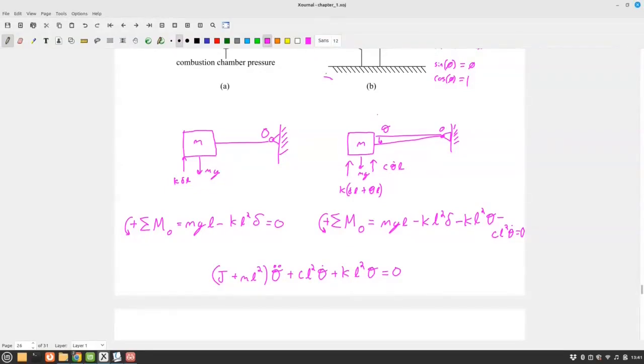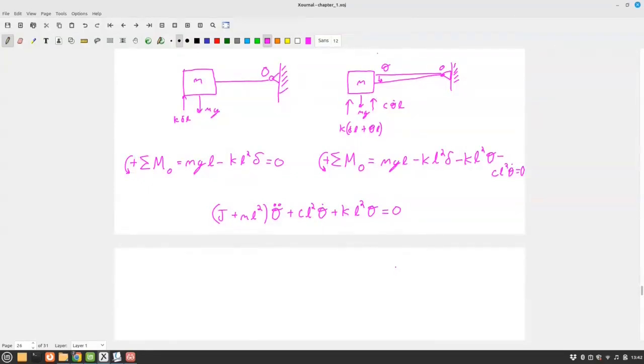Now, the standard form of the equation of motion is a term that I have, and I'm going to be honest, it's confusing. I asked you, let's find the natural frequency of this. How do I get the natural frequency? All of these terms are confusing, or at least it's just not in the standard form that we've been seeing. That's the power of the standard form. If I put this in the standard form, I need to divide by whatever leads my theta double dot, my acceleration term. I don't divide by the mass.